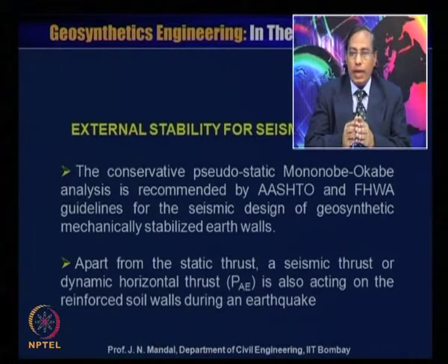Apart from the static thrust, a seismic thrust or dynamic horizontal thrust, designated as PAE, also acts on the reinforced soil wall during an earthquake. Most of the time we don't consider the seismic effect on the reinforced soil wall, but it is very important to consider it, because there are a lot of earthquake related problems on infrastructure.